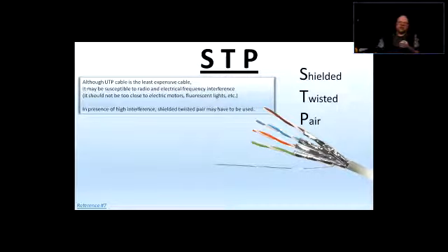Okay, try to stay away from that, at least 1 foot from anything that basically turns on. Right? Everything that is active electrically or electronically. So that's kind of a general rule. In fact, in some of the contracts, even when you receive the contracts, it's actually going to be specified that when you're running those wires, keep clear 12 inches or 1 foot, at least 1 foot, from anything that can produce electromagnetic interference.